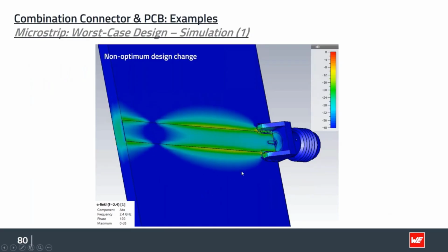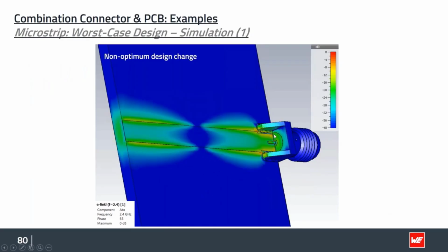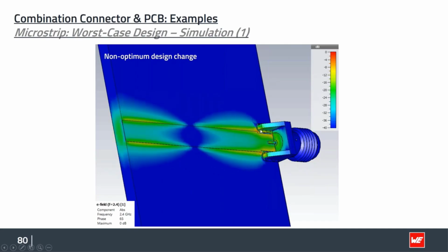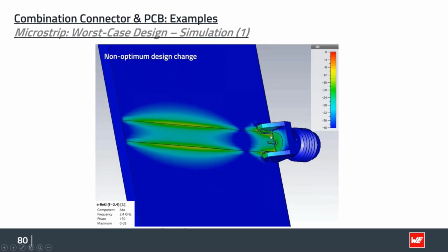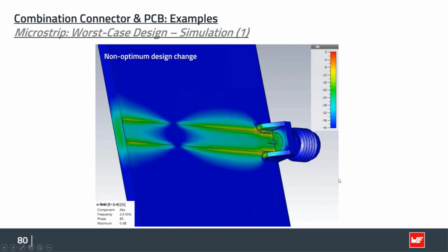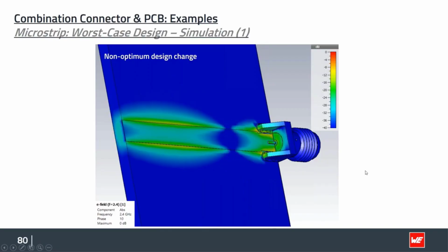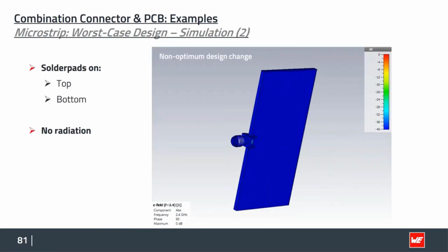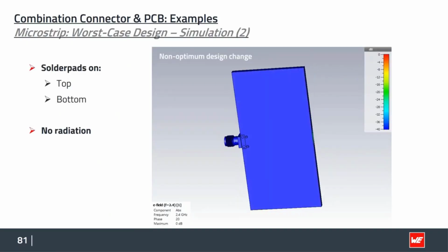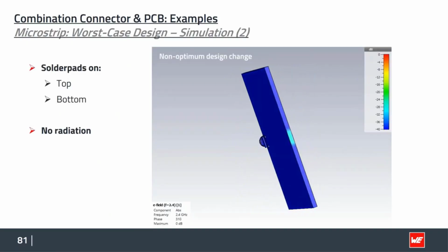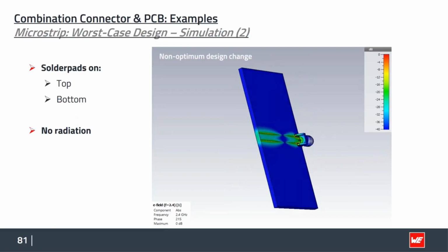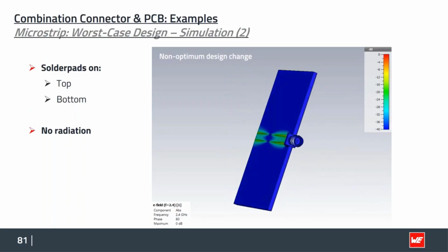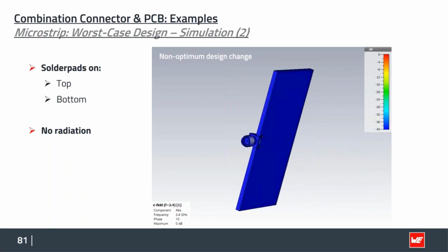So, we can still see that, of course, on different positions, we still have some red hotspots in here, like before. So let's see what impact our improvement had on our measurement. And we can see, yeah, it worked to close our slot antenna. That's a good sign. So no radiation anymore. The energy should be hopefully on our PCB track and not somewhere else on the PCB.